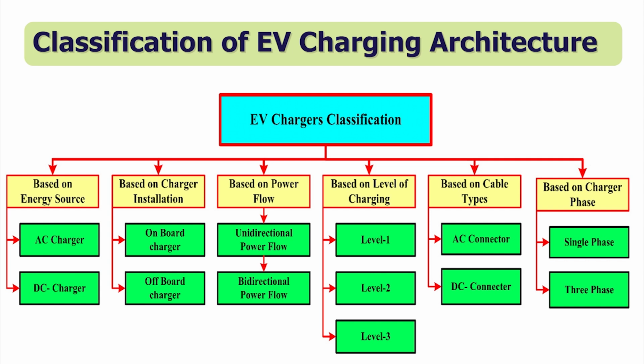and the battery unit is small, the power needed is only up to 3.3 kilowatt. So, we can go for single phase. However, if we talk about a semi-fast charger, then we need to integrate level 2 with 3 phase. As supply is available in single phase and 3 phase, we can integrate the charger with the single phase supply as well as the 3 phase supply.